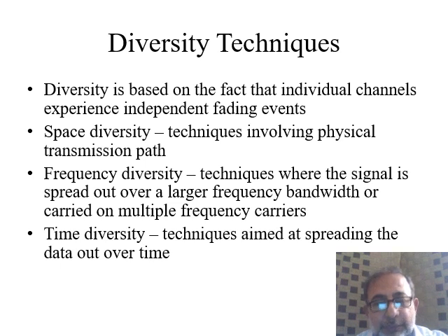Then frequency diversity, in which the signal is spread out over a large frequency bandwidth or carried on multiple frequency carriers. And CDMA and DSSS, the direct sequence spread spectrum method, which is used in 3G systems, and frequency hopping, that is also another example of frequency diversity.